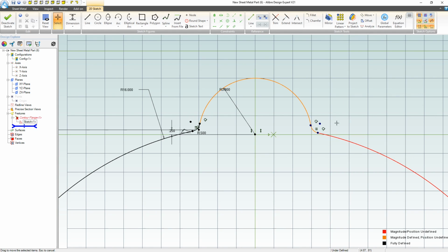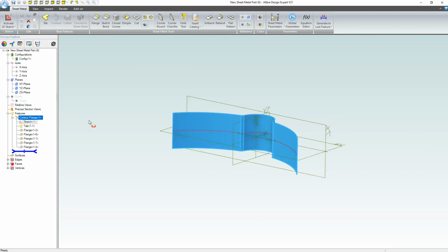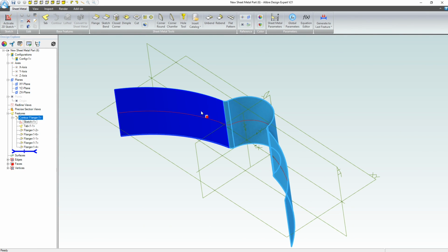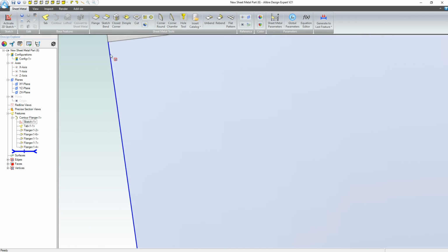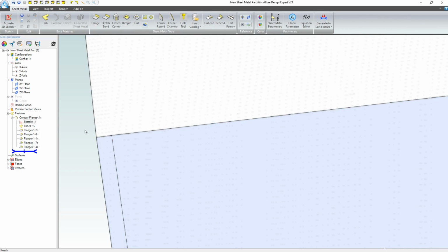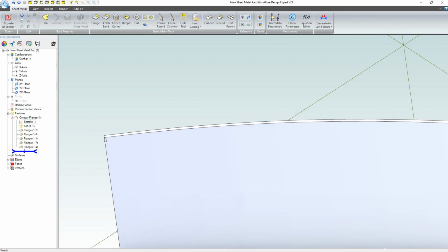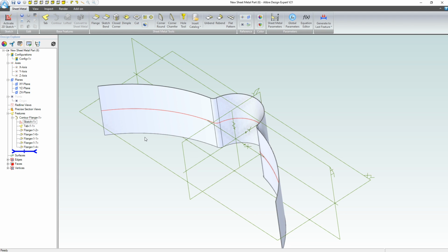constraints as we've defined that, so we'll simply add in a horizontal from here to here, and we're back to being fully constrained. We'll deactivate, and look at that, we've automatically generated our part. And can we flatten it? Indeed we can, again with our 1/1000th of an inch flat face that doesn't hardly show up anywhere, right? So that is way within the tolerances of a sheet metal part. We just need a little straight section somewhere.